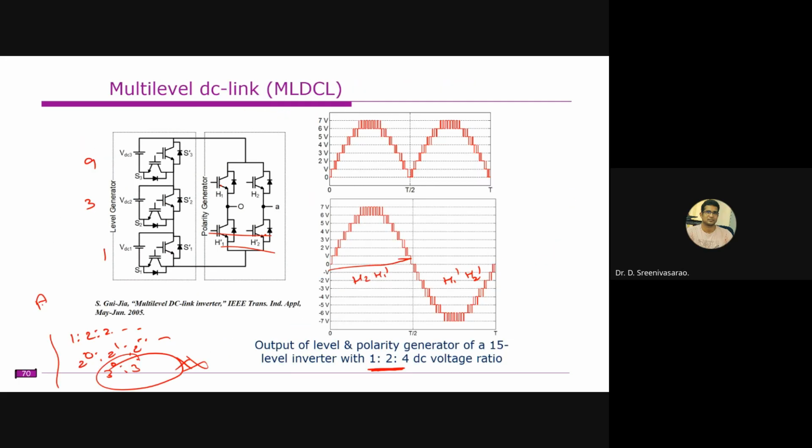Let us assume this case, right? This waveform is almost a sinusoidal waveform, therefore the THD is very much less, maybe 2%, 3%. Further, if you connect some small inductor or a very small LC filter, or the machine inductance, that is sufficient to make it pure sinusoidal. So depending on the voltage waveform, we can say whether the harmonics are reduced or not. It does not depend on the switches.